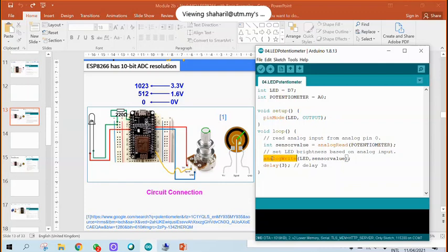That's why you call analogWrite. And then you delay for 3 seconds, 3,000. Not 30, 0.3 millisecond. Okay, so just right. Let's look what happened.